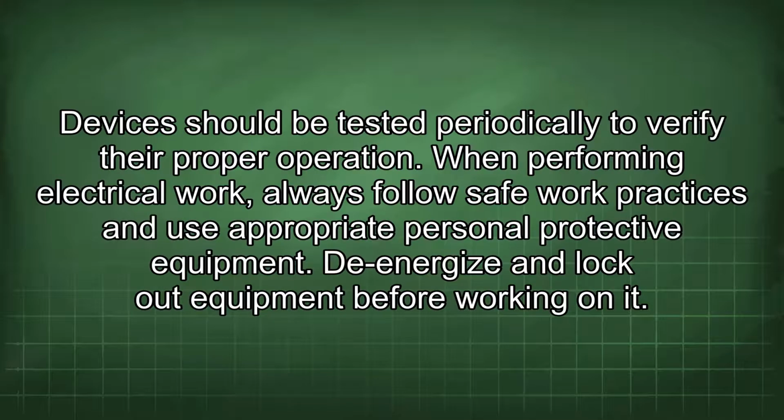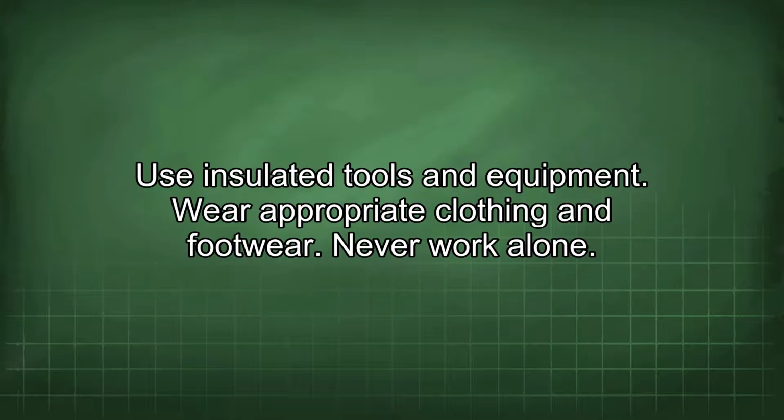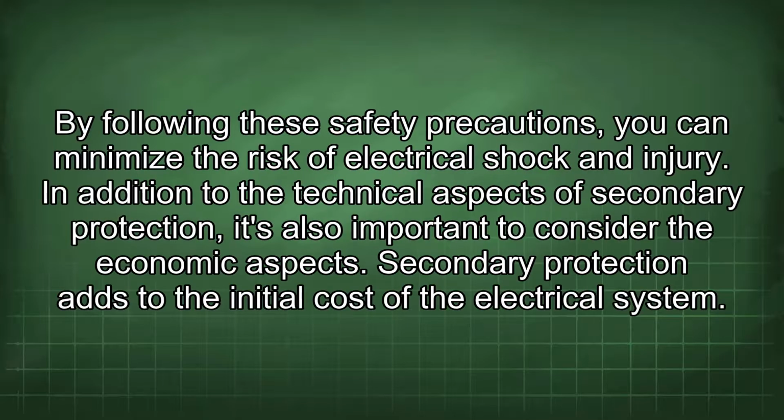When performing electrical work, always follow safe work practices and use appropriate personal protective equipment. De-energize and lock out equipment before working on it. Use insulated tools and equipment. Wear appropriate clothing and footwear. Never work alone. By following these safety precautions, you can minimize the risk of electrical shock and injury.